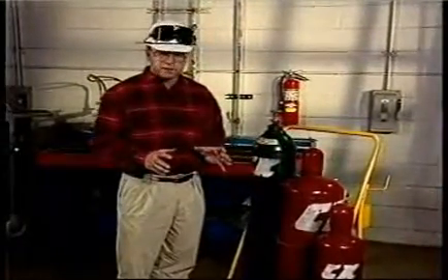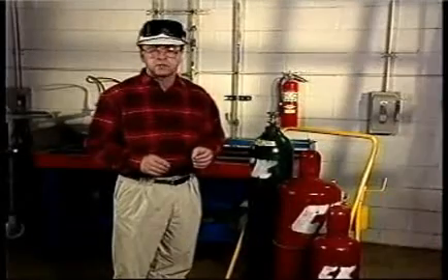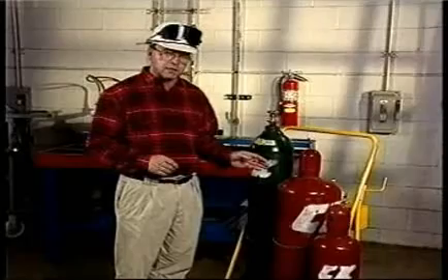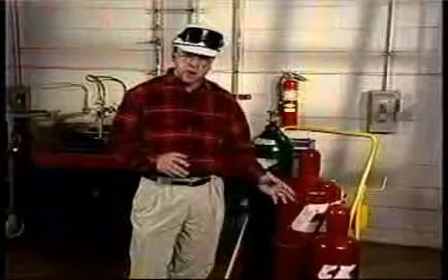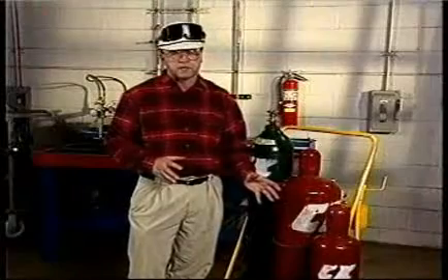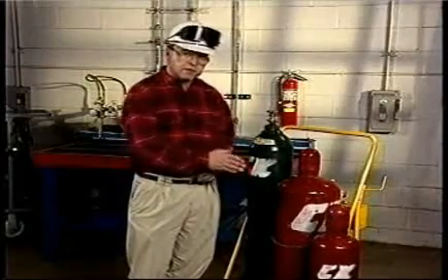So using the 1/7 rule, I can use up to 43 cubic feet in the first hour and not withdraw acetone from the cylinder. This smaller cylinder contains approximately 150 cubic feet of acetylene, and I can safely use about 21 cubic feet in the first hour and not withdraw acetone.